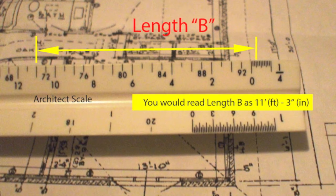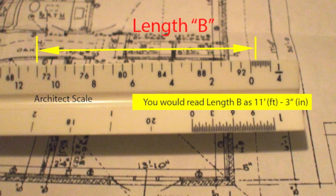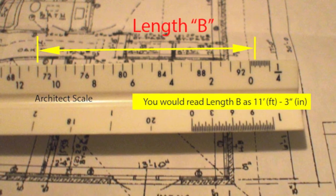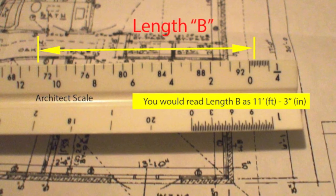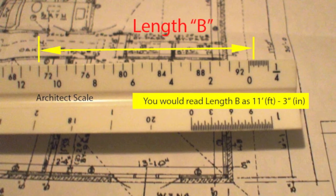From 0, simply count the number of tick marks to the right. I count 3. You read length B as 11 feet, 3 inches. Remember to use the correct ratio that matches the drawing scale you are sizing. Now, let's discuss the engineering scale.